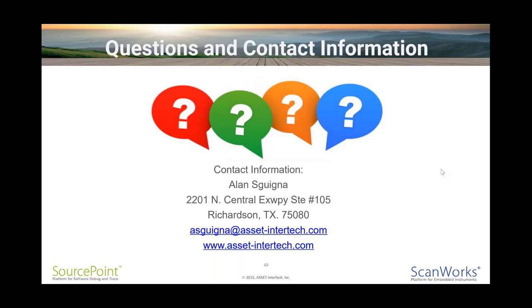Yes, I can, but not now. What you simply do, for example, the same approach, in the memory window itself, click on the byte or word or double word that you want, right click, and then edit. Very similar, the same approach that I showed for how the general purpose registers can be edited. And again, via the command language, the mem command, I believe, is the one that you would invoke to read batches of memory, system memory, DRAM, for example, and then make the appropriate changes. All of that is documented. The specific syntax and parameters are documented inside the command language description.